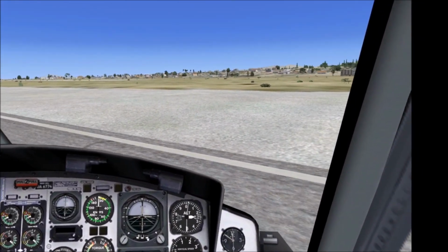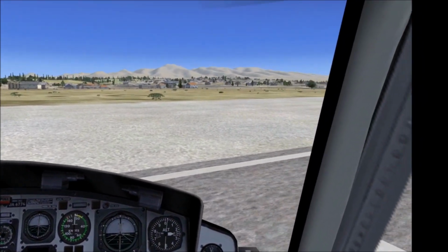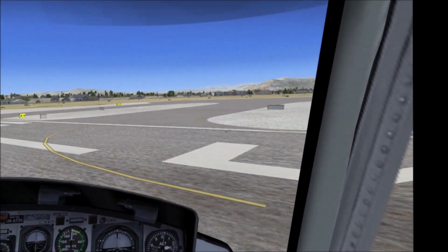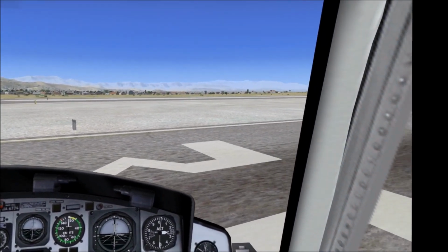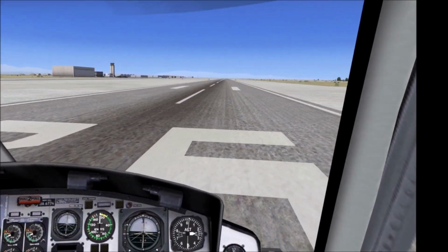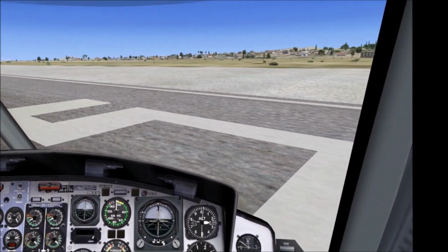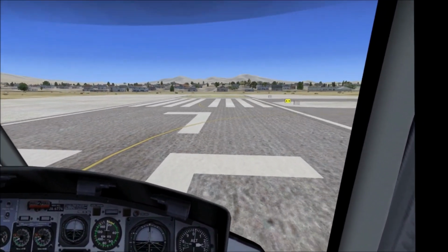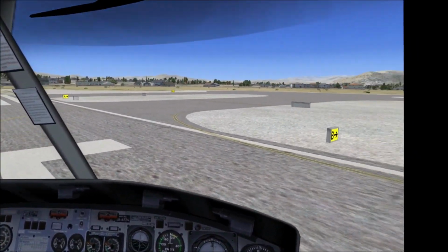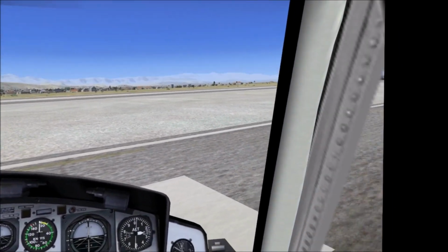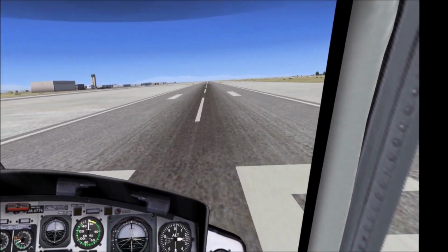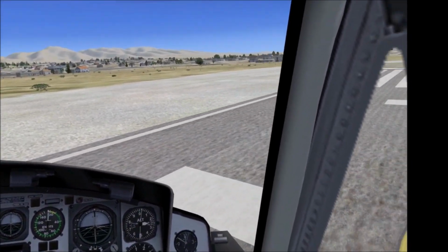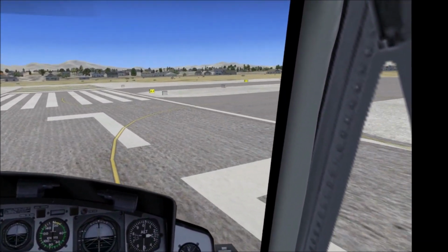I would expect a little bit more for an aircraft that doesn't have any sort of artificial or automatic flight stabilization. I would expect a little bit more than this. This just to me feels like a right pedal turn, to be honest with you, like something that's intentional, not something that's... this feels like a control input, because I could pretty easily get this thing back on the ground without damaging the aircraft. As you can see, during this I've been able to keep it right over the numbers here.